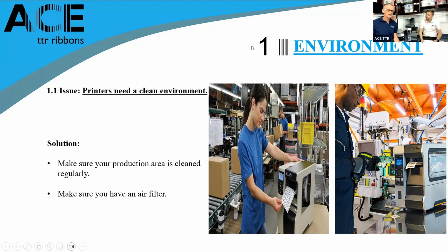I'd just probably add there, Vladimir, that we have a large printing client in Vietnam who was originally doing TTR printing in more of a manufacturing area. And then they noticed that they were spending quite a lot of money on printheads, as a lot of you do. They then built a simple but very clean filtered air area. They got about maybe 16 to 20 machines. And then they found in this clean area that they were getting printhead life extension of about 30%.